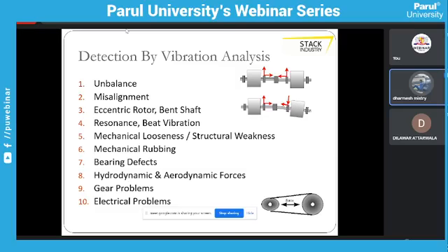Then another thing, for example, if there is a big motor and I am measuring the vibration from the top, the top vibration is an x-axis vibration. If the x-axis vibration is coming more than the y-axis and z-axis, the maintenance person will easily know that the mounting of the motor is weak. If the vibration in the x-axis is more, meaning up-down vibration in the motor is more, that means there is a structural weakness and the motor is not mounted well.